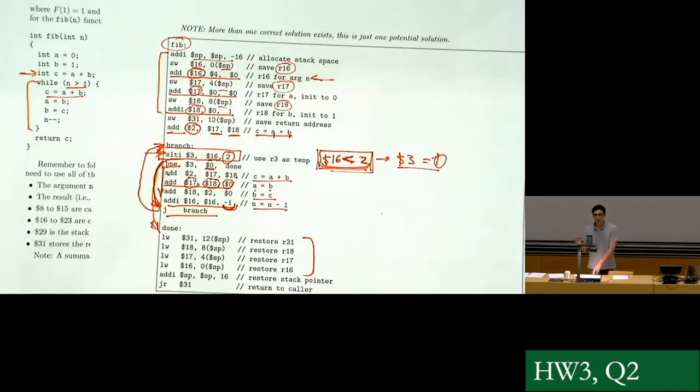It might happen that sometimes you're really using these registers, other times not. But it is safe to have this convention that those registers that are going to be used by the function are by default saved in the stack. And this way you avoid any possible overwriting.